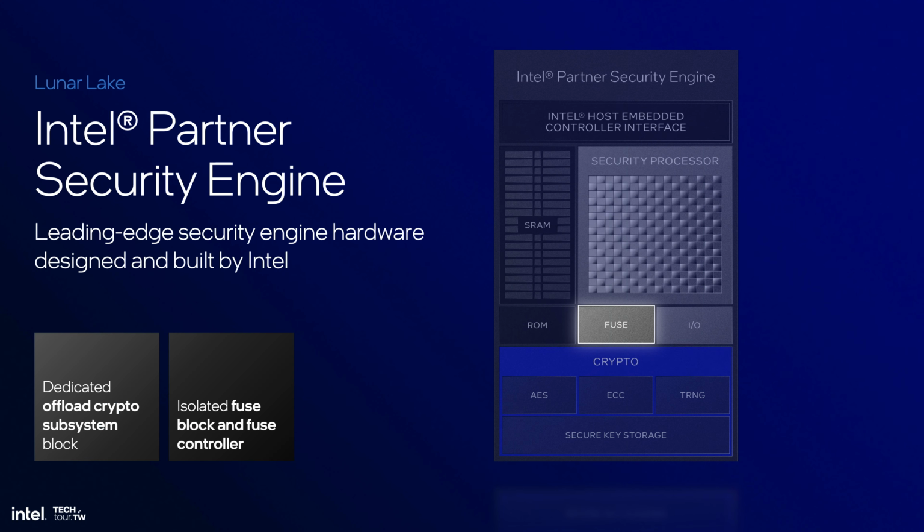Likewise, we wouldn't want our CPU fuses and our own Silicon security engine fuses accessible to the partner software or firmware, which is why the fuse block, or fuse macro as we call it in the integration world, is dedicated to this engine and is not accessible to other engines. And the access it initiates is through its own fuse controller. Traditionally, IPs would have used a fuse controller that's in the SoC.